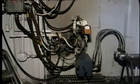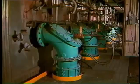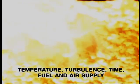Now, there are many different types of burner equipment installed, generally for different fuels, and perhaps for different grades of the same fuel. As we study these various types of burners, we should keep in mind that the objective in all cases is to provide the correct conditions for combustion, that is, temperature, turbulence, and time, and also to provide control over the supply and distribution of fuel and air. In this segment, we'll take a look at combustion equipment for burning liquid and gaseous fuels.